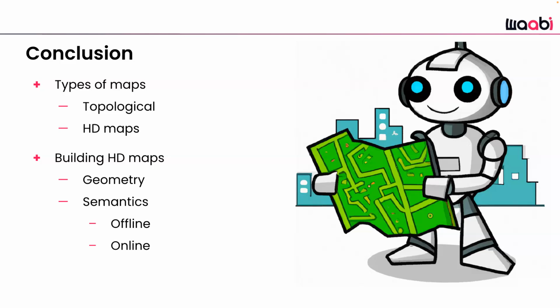You can also build maps with radar. They're a little trickier to build, and you need to remove the noise before you accumulate the data. But then you have the benefit of maps that are by design more resilient to weather conditions, like fog, that you can then localize to.